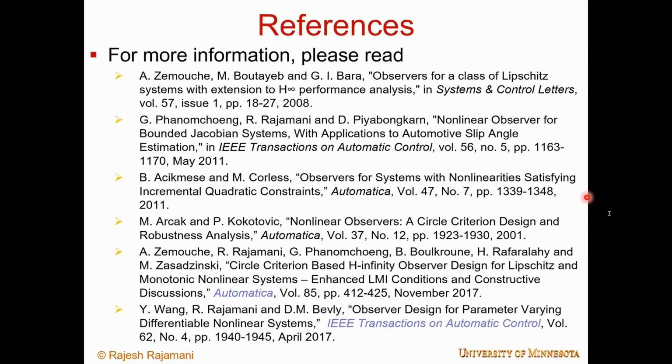So I think we saw in one of the data plots that I showed you that the system clearly exhibited nonlinear behavior, meaning there was saturation in tire forces with slip angle. So of course you could do linearization and, for example, use an EKF. We haven't, for this specific application, done an extensive comparison between a linear observer and a nonlinear observer, but for some other applications we have.